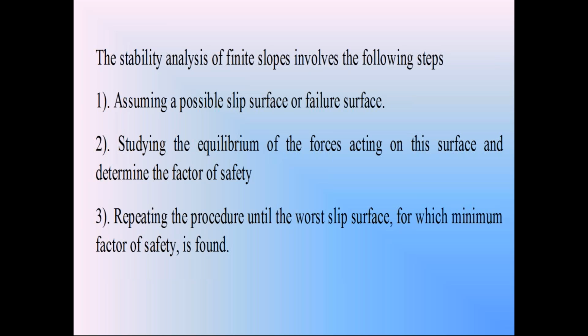That failure surface may be a straight plane failure surface or an arc of a circle. Consider one arc of a circle in the plan as the failure surface. Then, considering the portion of soil between the finite side slope and the failure surface, find out all the forces acting in the side wedge. The side wedge is in between the side slope and the failure surface.